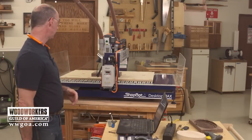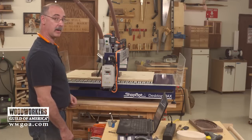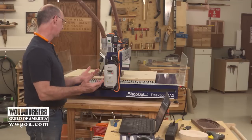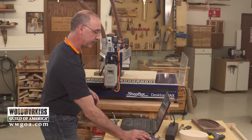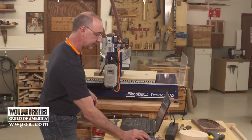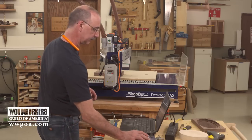New board in place, 1¼ inch thick. I zeroed my X and my Y over that mark. I then also zeroed my Z down to the surface using the touch plate. Next step, call up the right file here. And remember, these files are going to run back to back because we put them both in the same file. So they're going to run one right after the other. That's the lid again. Let's look here for the bottom. I've already got the spindle turned on, so we're good to go.